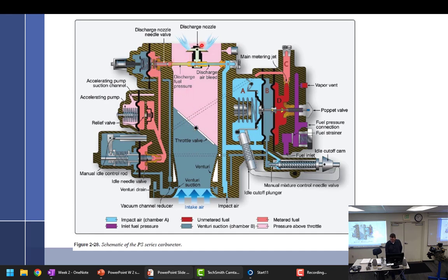The discharge valve is spring loaded with a diaphragm. The spring keeps the valve closed until proper pressure opens it, so we don't have fuel dribbling in and making a mess. Once we get proper pressure, with the vacuum plus the fuel pressure hitting the diaphragm, bang, it opens and fuel starts to flow. When pressure decreases, the valve closes to do what?